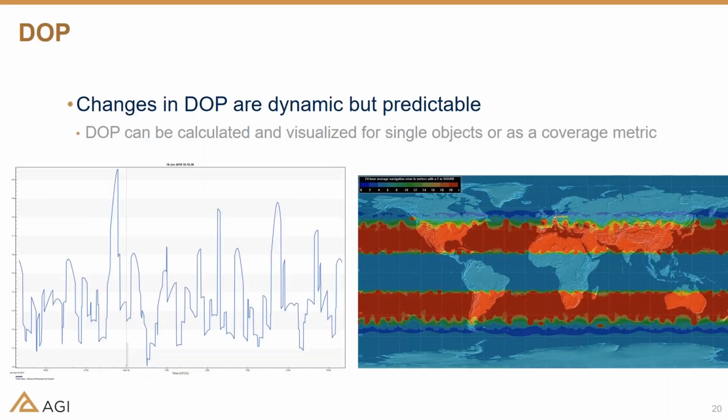So let's go back and look at DOP. We talked about the fact that DOP is a result of the satellite positions in space and their orientation. What I didn't talk about was what good DOPs and bad DOPs are, if you're not familiar. A bad DOP would result from all the satellites being in a straight line across the sky, for example. Good DOPs would be pretty much the opposite of that, having satellites equidistant around your horizon and then satellites directly overhead as well. That'll give you both a good HDOP and a good VDOP, or horizontal DOP and vertical DOP.